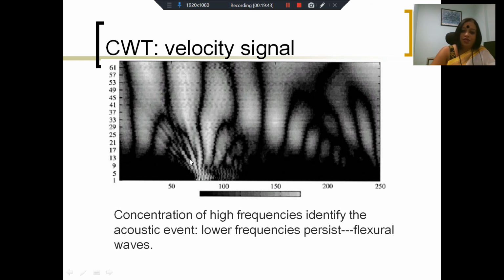And therefore, what we can do is, if we can do a high frequency measurement, we will not only be able to probably work with a good signal to noise ratio, we might also be able to locate in time exactly when this emission occurs, and that will give us a measure of what distance these frequencies have had to travel to the sensor.